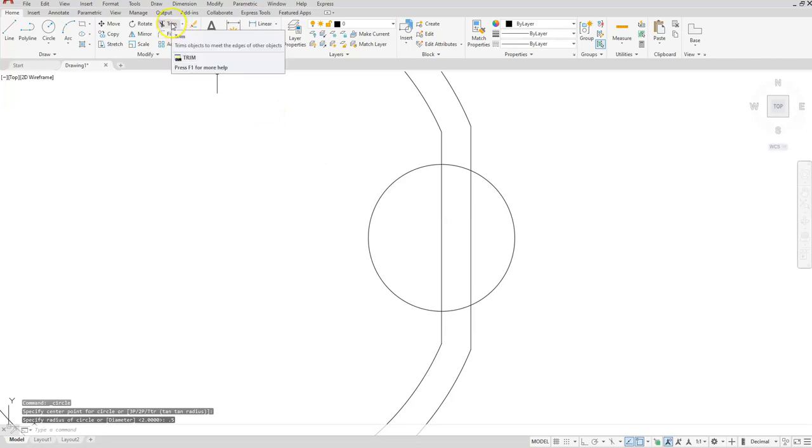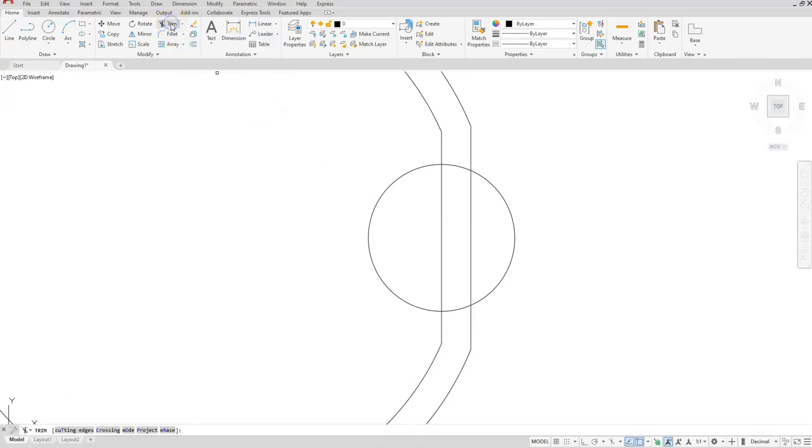Choose the trim command again. Well, before we use the trim command, let's go ahead and make the lines, and then we'll trim it and make it one command. So let's start the line from this quadrant out to where it perpendiculars to this line. Then escape. Do the exact same thing on the other side. So line from this quadrant to where it perpendiculars to here.